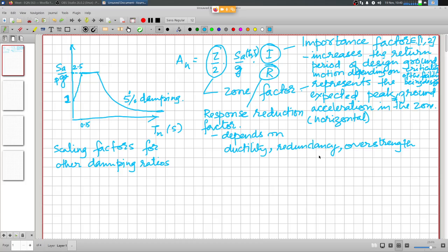Isn't it? Doubly reinforced sections are always over reinforced sections. So that is of course theoretically yes, it is going to be over reinforced, but not of much practical concern. Practical issues are somewhere else.